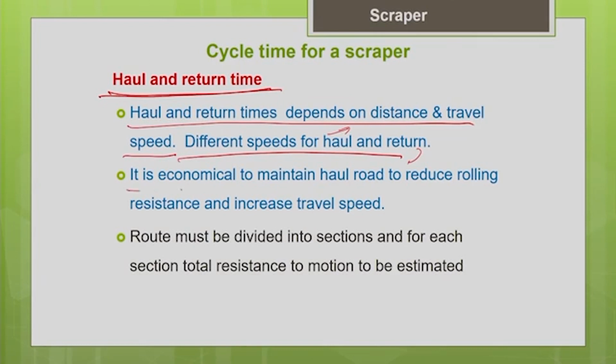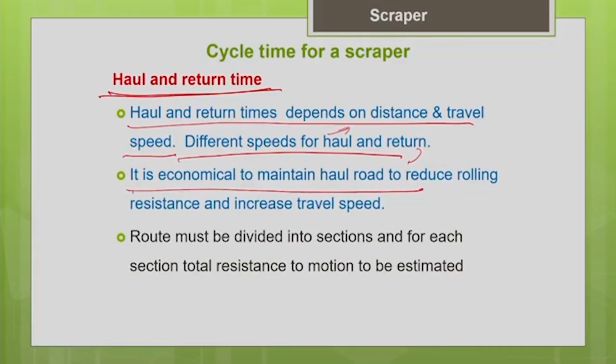So, it is economical to maintain the haul route. Whatever efforts, whatever money you spend for maintaining a haul route, it is going to give you good return by saving your cycle time, by increasing your productivity, and thereby it will reduce your unit production cost. It is economical to maintain the haul route to reduce the rolling resistance and increase the travel speed.